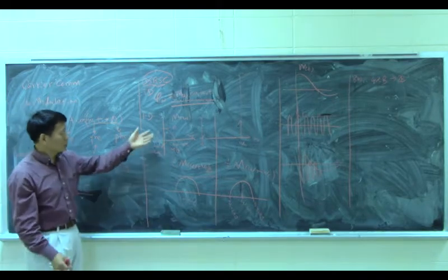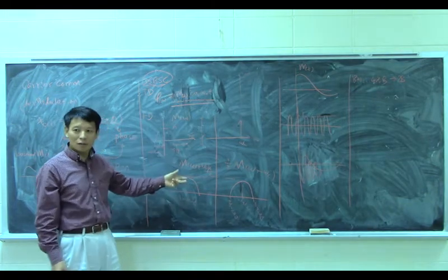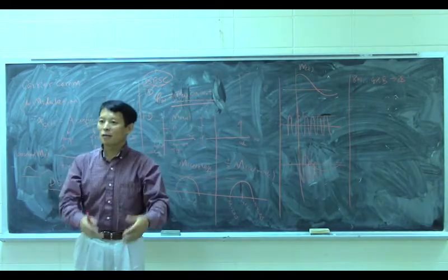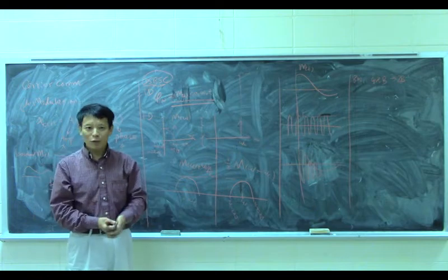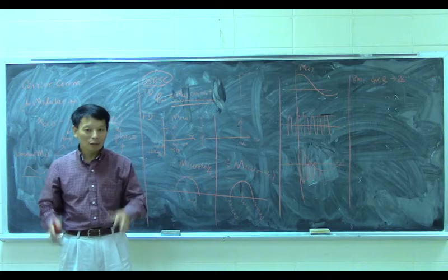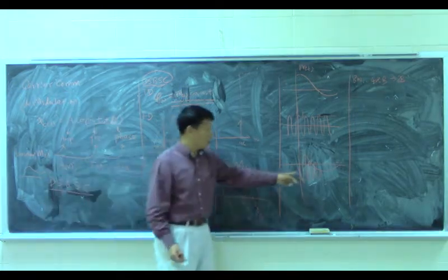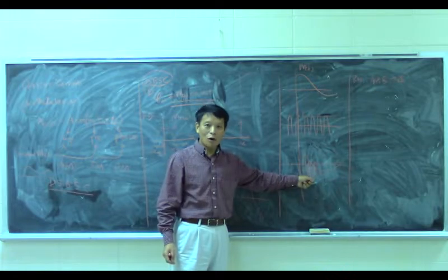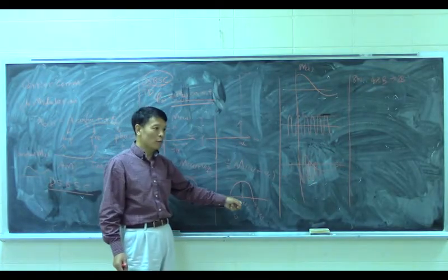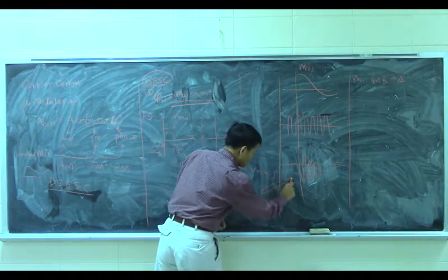Suppose you have your voice baseband m(t), you modulate this. That means in time you just multiply with the cosine function. In frequency you shift to a higher frequency band. Then at the receiver, you are going to receive the time domain signal like this, or the frequency domain signal like this. They are the same thing, right? These two are the same.